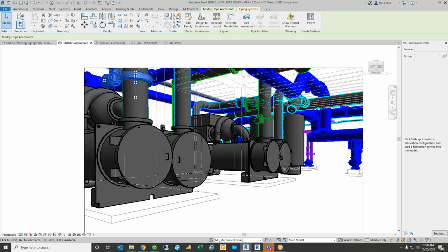And is there a relationship between LOD and ANSI? So you have an ANSI specification for valve dimensions. Is LOD 350 aligned with that or what? So the component libraries that end up in the software that are supposed to be the fabrication parts, the LOD 350 parts, use the dimensions out of the ANSI standard documents for that component.